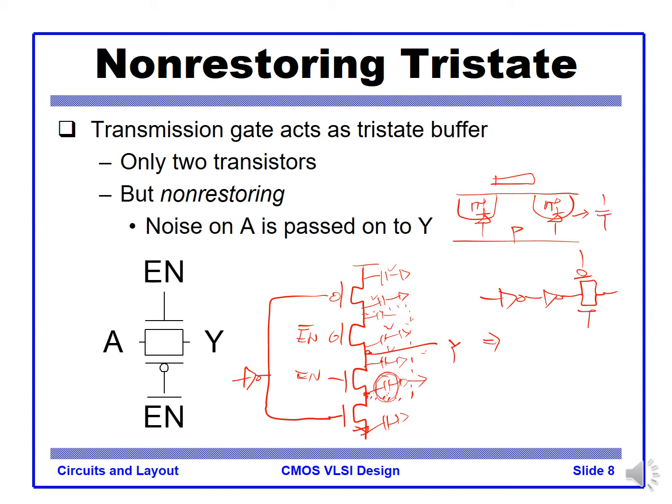But in this implementation, we have to charge all of them. If we connect between those two, all those internal parasitics need to be driven to VDD, or to ground in the case of the pull-down. So it slows down. In most cases we prefer not to add this kind of connection in the tri-state buffer. You can see the speed difference in simulation.